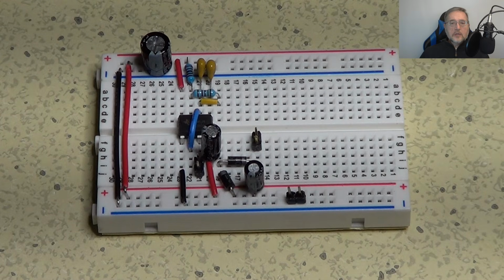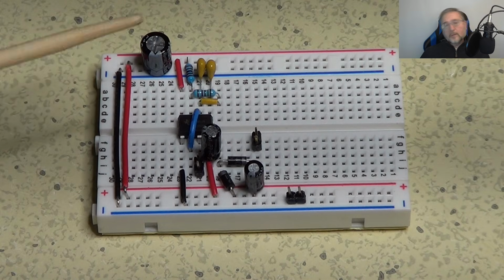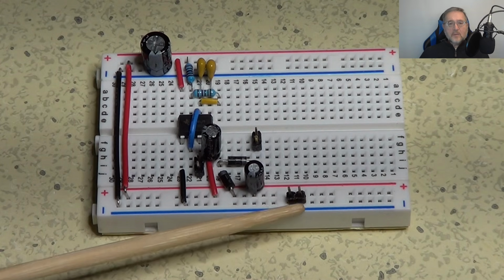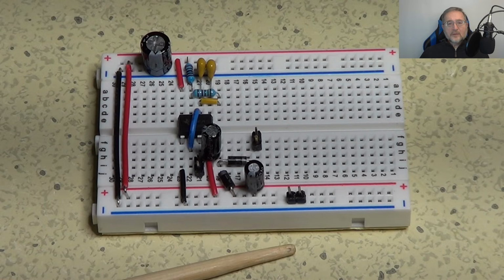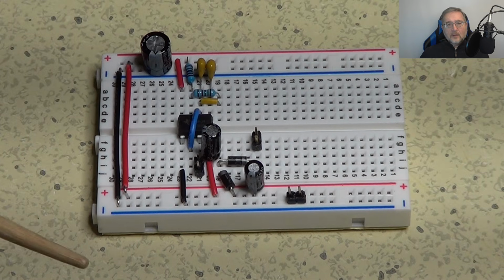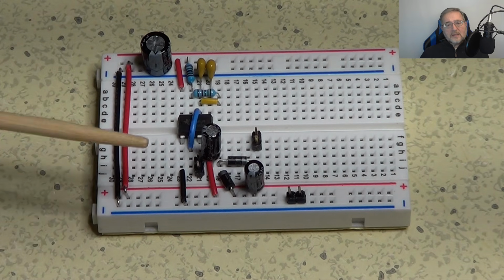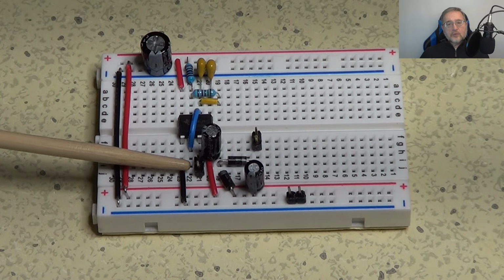And the frequency should be around 3.7 kHz, besides the tolerances of the components, of course. I also added 3 pin headers. I will use this one to connect the instruments to the ground of the circuit. This other one is the actual output, and the last one, connected to pin 3 of the 555, is the one that will allow us to check that the signal is an actual square wave at 3.7 kHz.